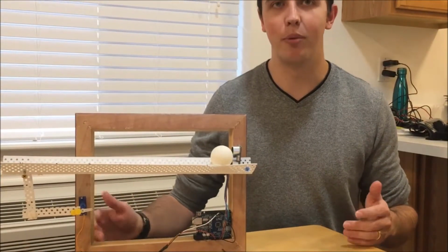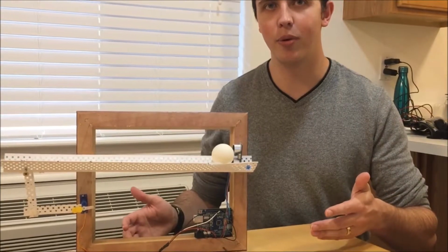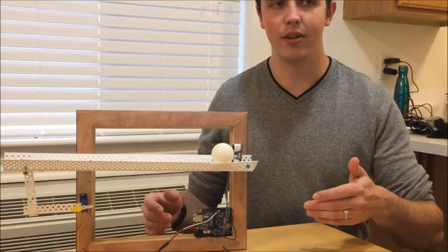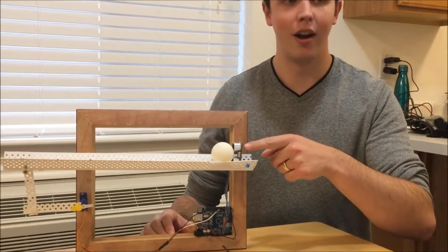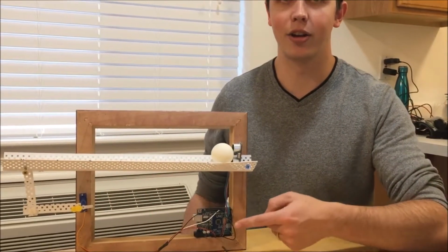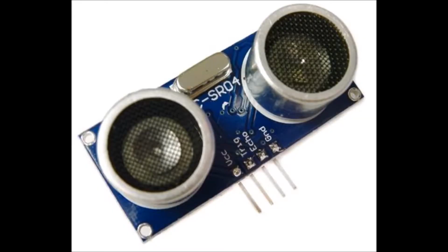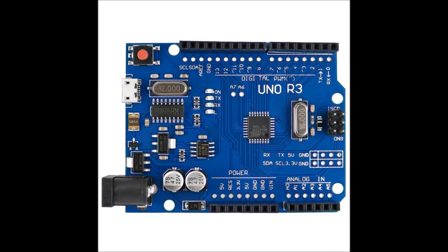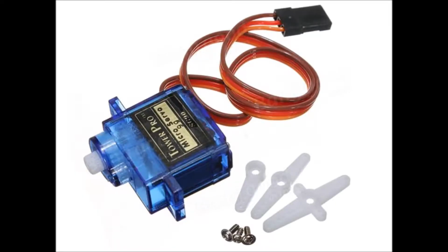The main parts of our project that allow us to control the set point, or control the ball, are our sensor, our actuator, and our controller. As we can see from here, we're using a sonar proximity sensor to determine the position of the ball along the beam, and every fraction of a second this position will then be grabbed by our Arduino Uno chip, which is our controller. This controller will then communicate between the servo motor and our PID controller to determine what slope the ramp needs to be at in order to adjust for the position of the ball to hit the set point.